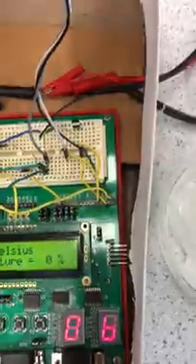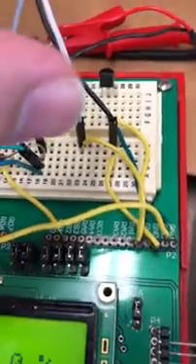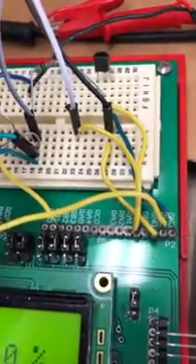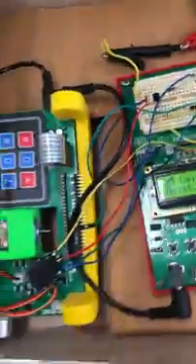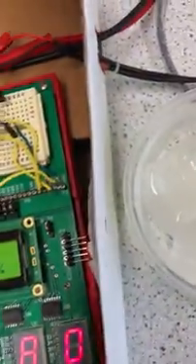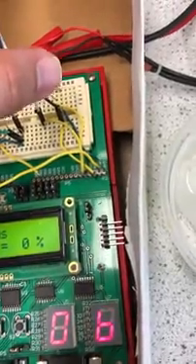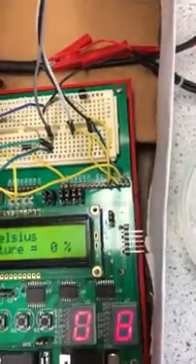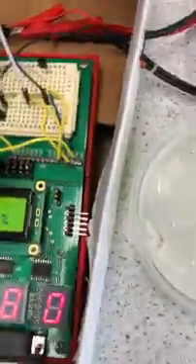Talking about the connection, the rightmost pin has gone to the ground, and the center one is connected to the resistor, which is further connected to the 5 volt, which is coming from this sensor board. The 16 pin is the 5 volt pin, and the resistor is connected to it, and one more wire is going to the RA0, which is a port given for the temperature sensor. So this is the connection of the temperature sensor.